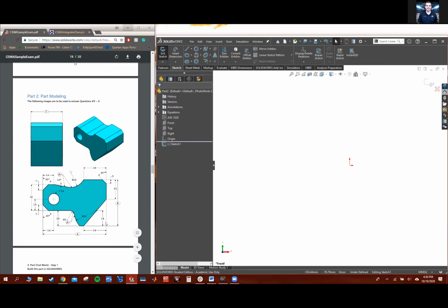You can put it in a bunch of different places. It really comes down to how much it's going to help you out when you start dimensioning off this stuff, like putting out this length or this length. So I'm going to choose my origin to be in this bottom left corner, just because all these leads are coming off this way. But you could put it right here. You would have to do a little bit of math to get all these lengths out. So yeah, I'm going to choose this bottom corner.